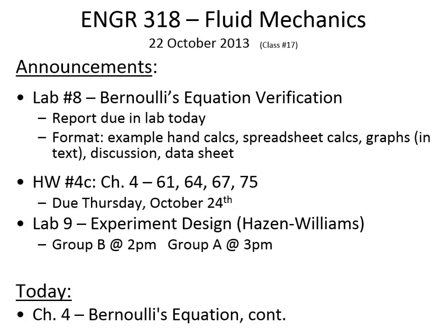The EGL, energy grade line, is going to be the pressure head divided by gamma plus Z, so what you actually observed, plus the velocity head, V squared divided by 2g. We can calculate the velocity in the pipe because we know the diameter and the flow rate.